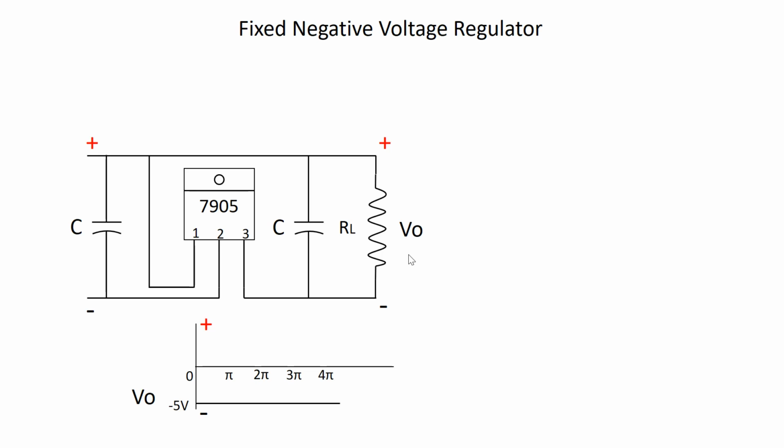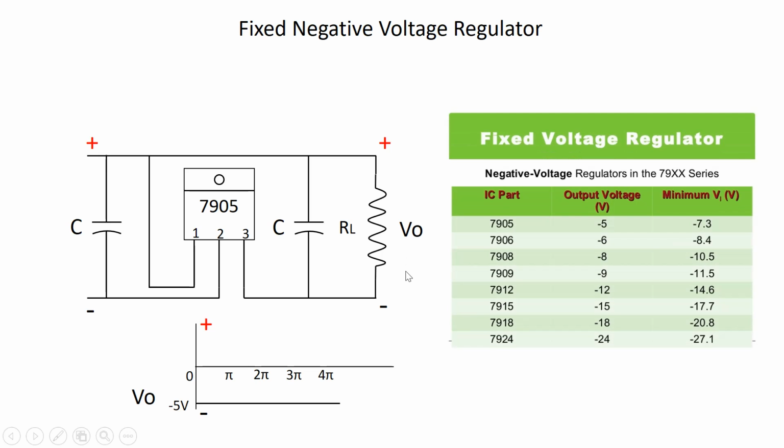Different ICs of this 79 series are tabulated here for your reference, and note down the output voltage range; the minimum voltage ranges are also mentioned here. The maximum voltage range can be referred from the previous table of the 78 series, wherein the polarity would be minus here. With this brief summary, we will close the narration of the filters and voltage regulator circuits.